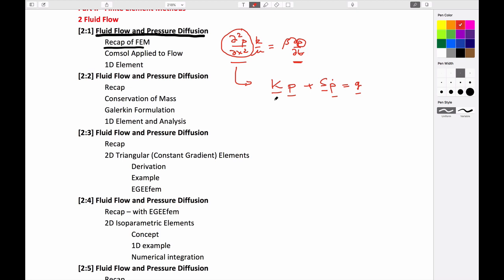And we made the case that these second order terms that operate on the pressure always have the same form in the finite element statement, that they are something like A transpose dA integrated over the volume, where this matrix is something that links, in this particular case, velocities to gradients of pore pressure, which we call P comma or H comma.